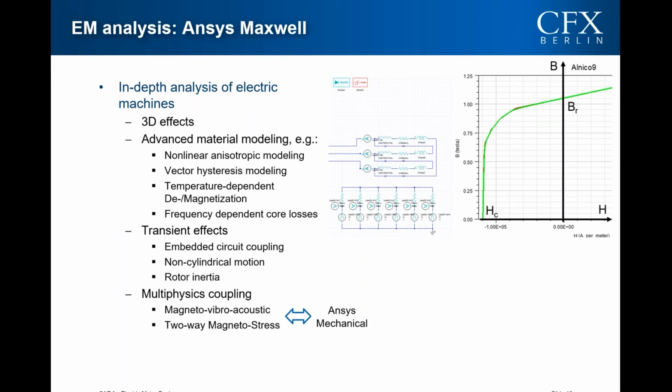There are also phenomena that need a coupled calculation between different physical areas. Examples are magneto-vibroacoustic effects and structural stress caused by magnetic forces. For these applications, we can couple Maxwell with ANSYS Mechanical.